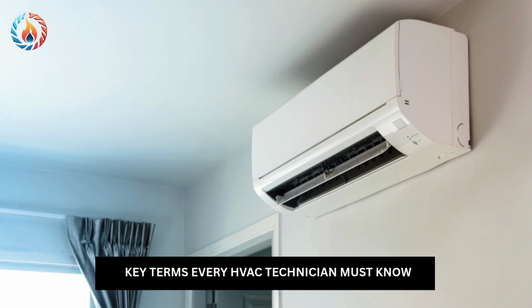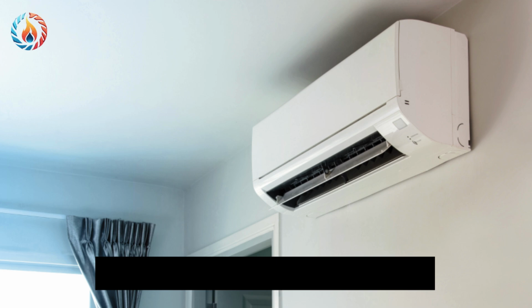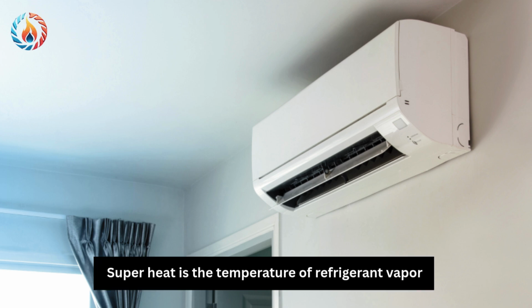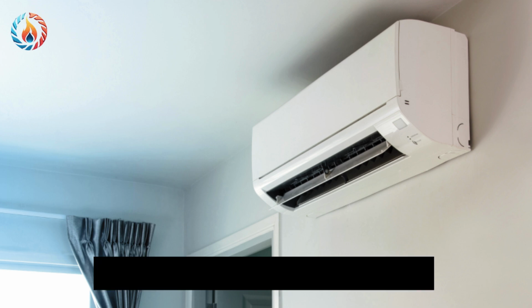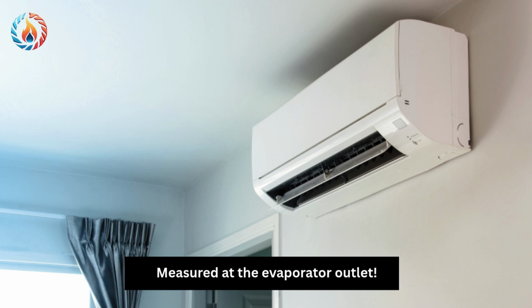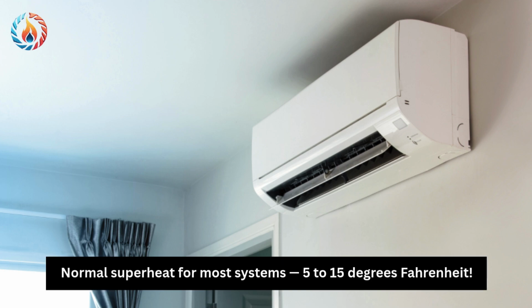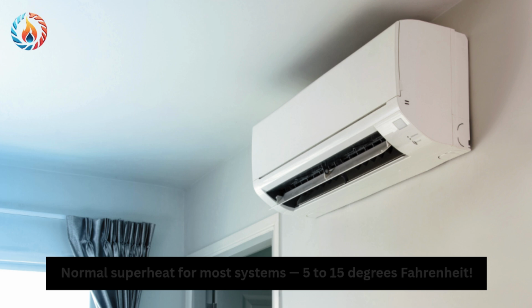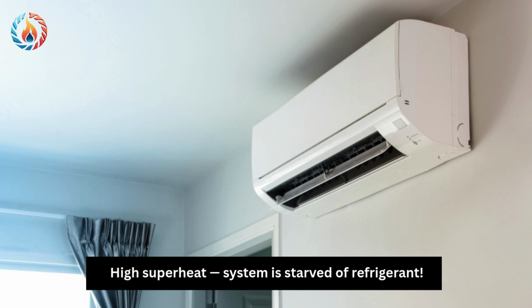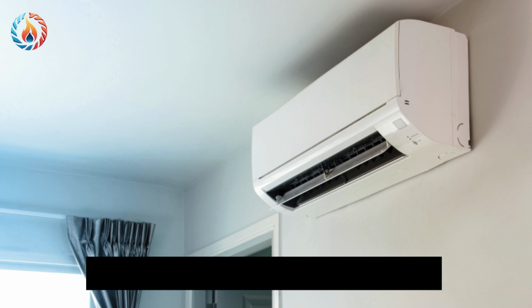Key terms every HVAC technician must know. Guys, these terms are asked in every HVAC interview. Superheat. Superheat is the temperature of refrigerant vapor above its saturation temperature at a given pressure, measured at the evaporator outlet. Normal superheat for most systems, 5 to 15 degrees Fahrenheit. Low superheat, liquid may be entering compressor. Dangerous. High superheat, system is starved of refrigerant.